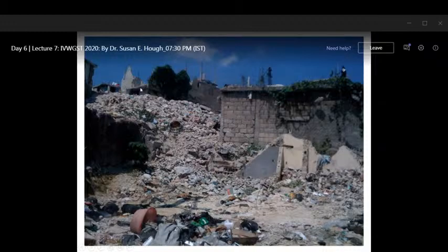I didn't include a slide, but if you think about a small hill or a ridge, energy can also get trapped in a topographic feature. It's almost like a building response. If you shake a hill, it's going to have its own response, potentially its own resonance, and that can give rise to amplification. It depends on the size of the hill, for example, what frequencies are going to be amplified. So it's a hard rock effect. It's not a consequence of having soft sediments, but it can also be very important for the distribution of shaking.